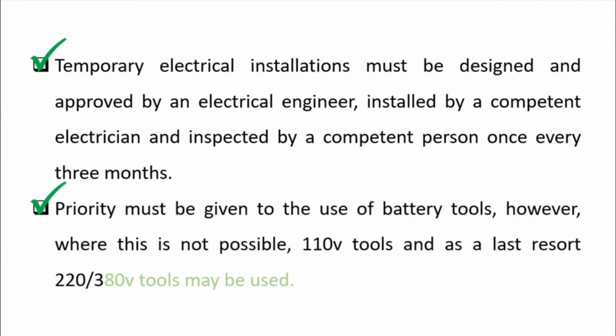Priority must be given to the use of battery tools. However, where this is not possible, 110 volts, and as last resort, 220 or 380 volts tools may be used.